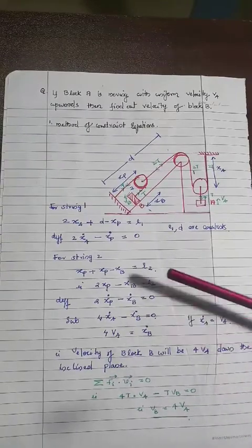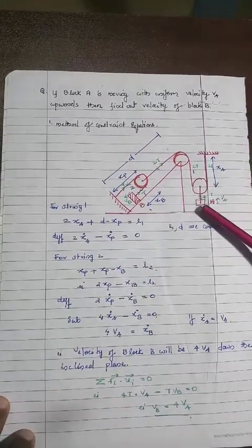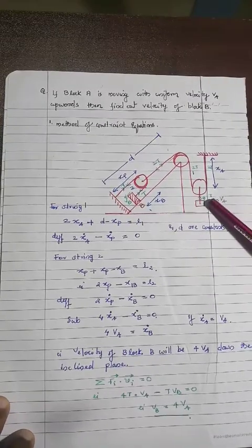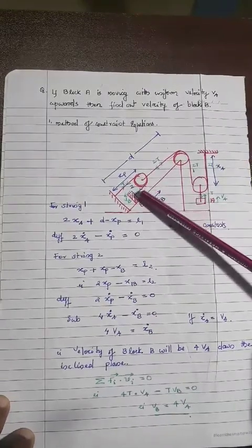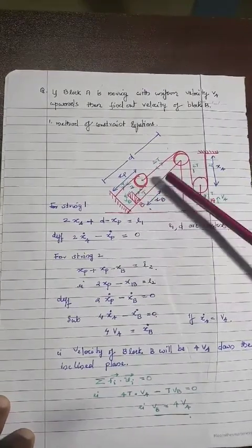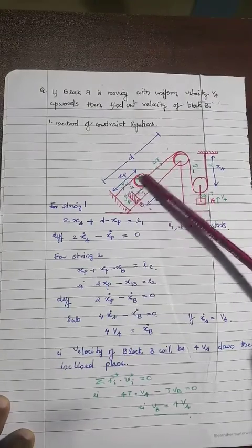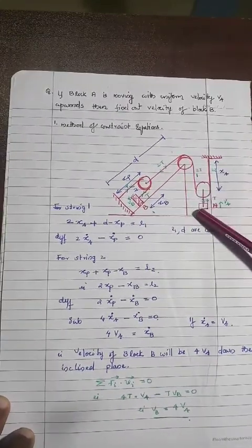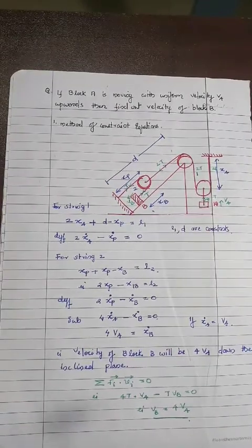But again, another concept, by using the method of virtual work, the movable blocks are A and B. And look here, in the direction of tension, 4T into VA minus T into VB. Look at the figure, how it becomes 4T and T. So this string is taken as T. Then here it must be 2T. But it is connected to another one, so that must be 4T. So you get the answer. And these two examples will give a good idea about the two methods.